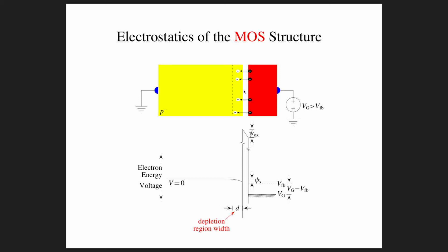And then we change to a different type of material. So we go from silicon to silicon dioxide. And it turns out that the electric field boundary condition when we cross a dielectric is something we talked about when we put up those three basic relationships of electrostatics, and I said it was sort of related to Snell's law, but the product of the electric field times the permittivity of the material is conserved across this boundary here.